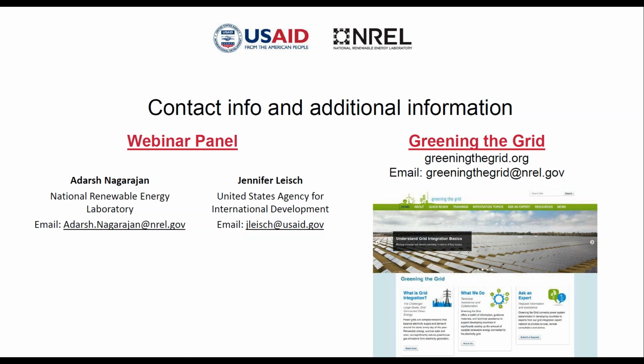So in the end, what makes things compliant in the US is UL, Underwriters Laboratories, which says that every inverter should go through UL 1741 SA, which means all these devices should behave a particular way. That's in the US. In other nations, there will be their local standards, maybe ISO, maybe something else.